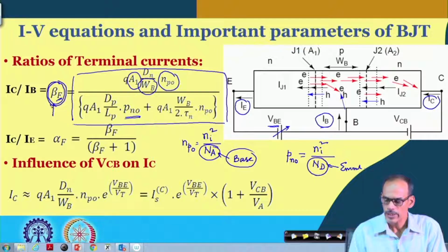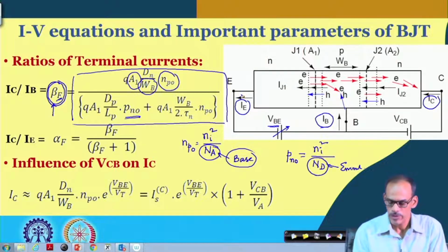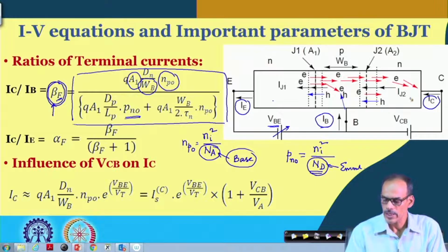On the other hand, if we pretend the collector terminal is the emitter and the emitter terminal is the collector, then instead of the emitter region, we have to consider ND of the collector region, and its corresponding concentration is quite different from the emitter.